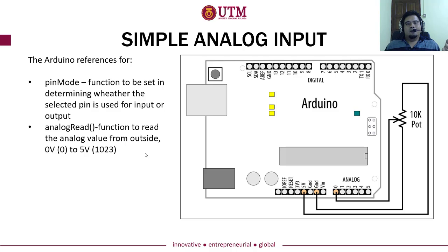So again, why does that happen? It is because your CPU is only allowed to process the digital signal, the integers or the discrete value. The continuous value cannot be accepted, which is why in your programming, the range of analog signal from 0 to 5 volt has been converted into the value of 0 to 1023, whereby 1023 represents the 5 volt in analog electrical signals.